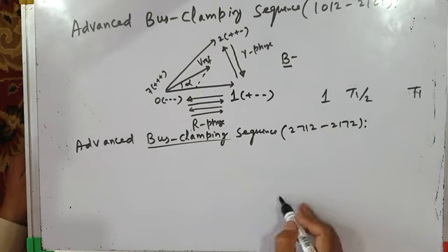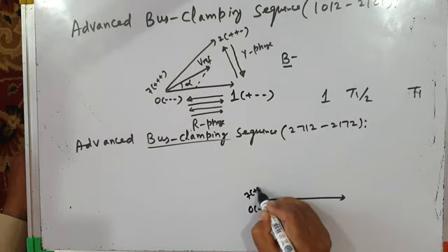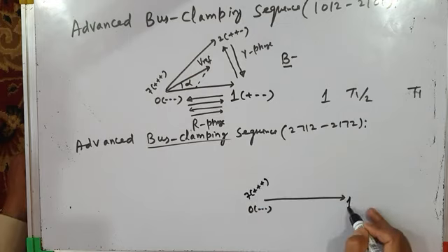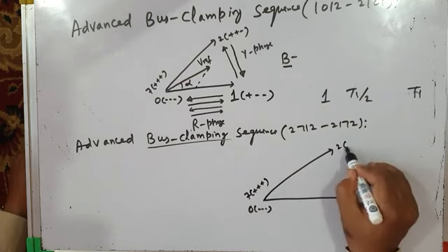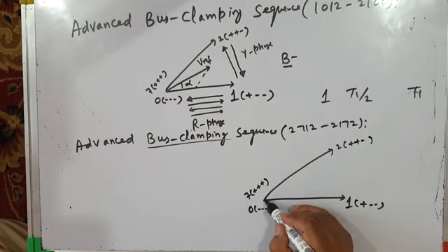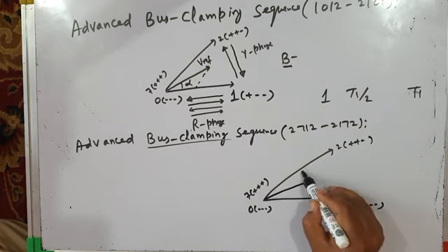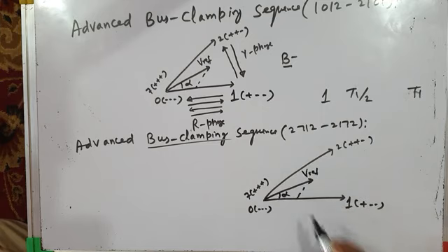We'll again take sector 1. This is null vector 0. This is null vector 7 with switching sequence plus plus plus. Active vector 1 plus minus minus. Active vector 2 plus plus minus. Time averaging of null vector and active vectors synthesizes the rotating reference vector Vref. This is spatial angle alpha. Vref is at an angle alpha.